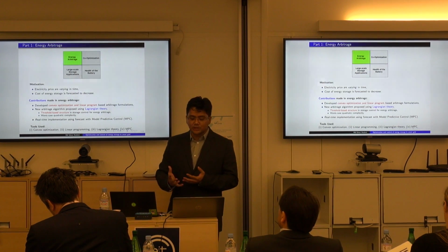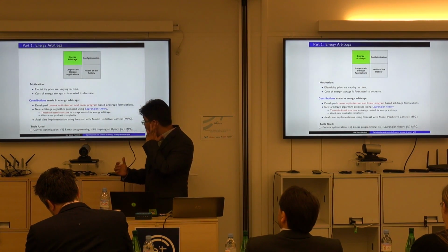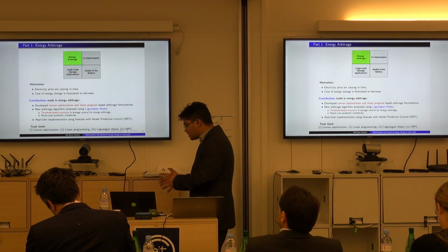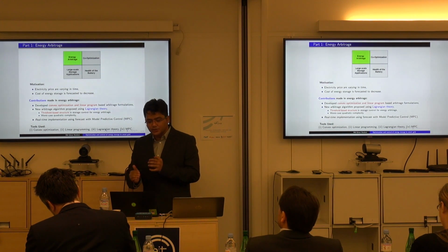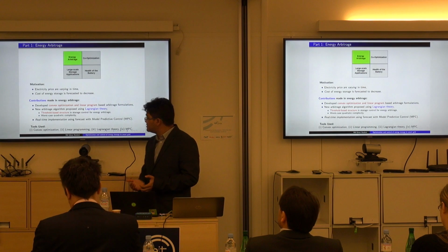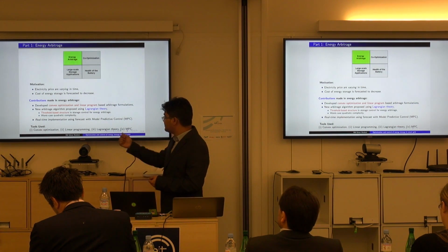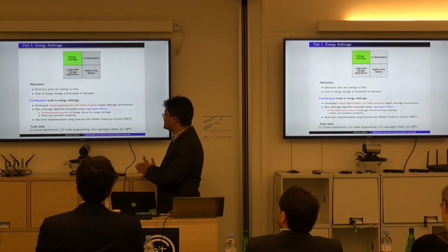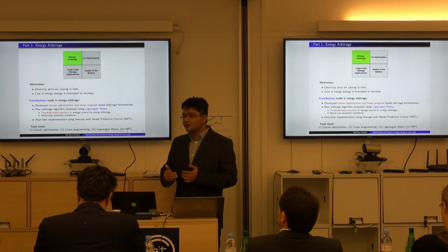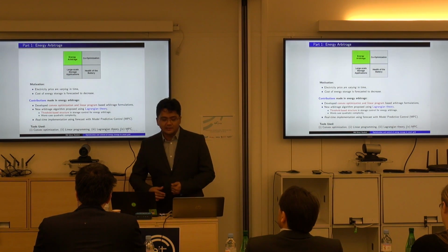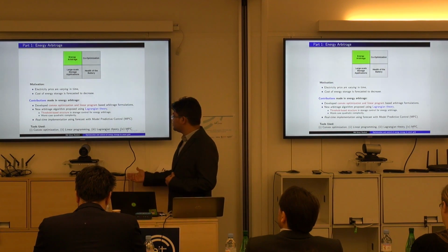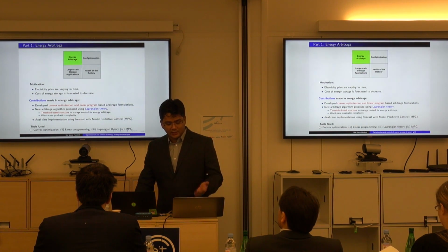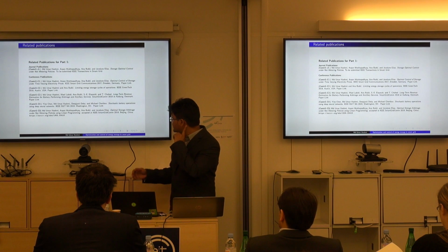and then compare these formulations with a new algorithm which uses Lagrangian theory. And there are two properties. Using this structure, we identify that the optimal solution of operating batteries under time-varying prices has a threshold-based structure. So we exactly quantify these thresholds, and because we identify this structure, we can explicitly find the worst-case complexity, which is quadratic for this algorithm. Then we extend this formulation to a real-time setting using forecasts along with MPC. The publications related to this part of my thesis are listed here.